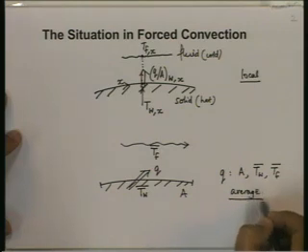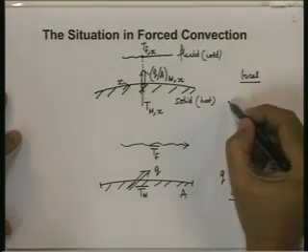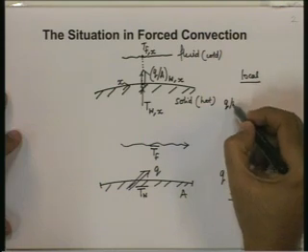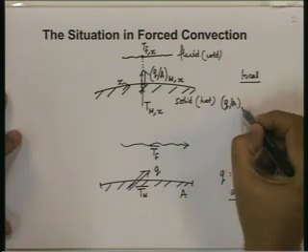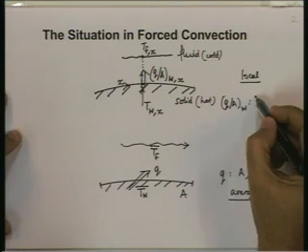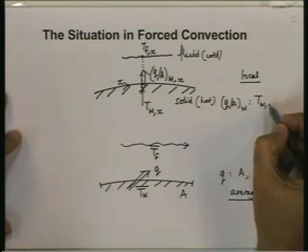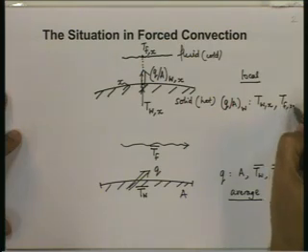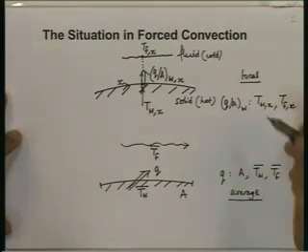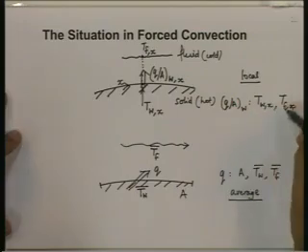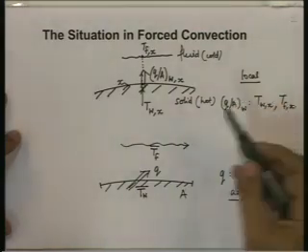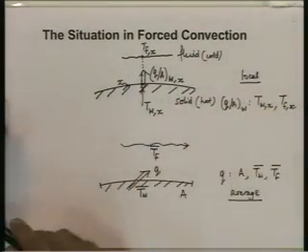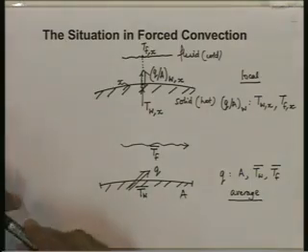whereas this is the average case. Whereas here we would like to relate heat flux at the wall to temperature of the wall at that point and temperature of the fluid at that point. Naturally, this will not be related only to this, it will be related to the geometry, the flow rate of the fluid, the local velocity of the fluid and properties of the fluid.